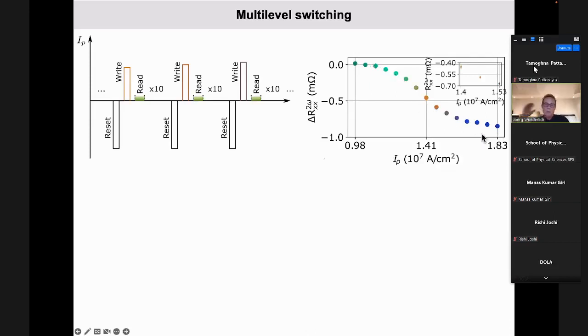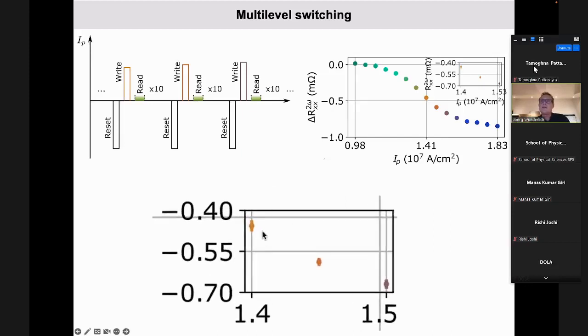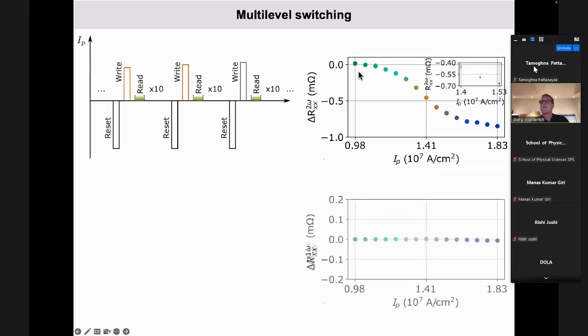We are back to our memristor, our system, which can act like a counter, where we have not only 1 or 0, but we have an analog memory, if you want. And if you look at the statistics we did, the measurement uncertainty is much larger than the uncertainty just from doing 10 measurements. So after polarizing the full system using the same kind of pulse, we switch exactly into the same intermediate state. So it's an extremely reproducible system.